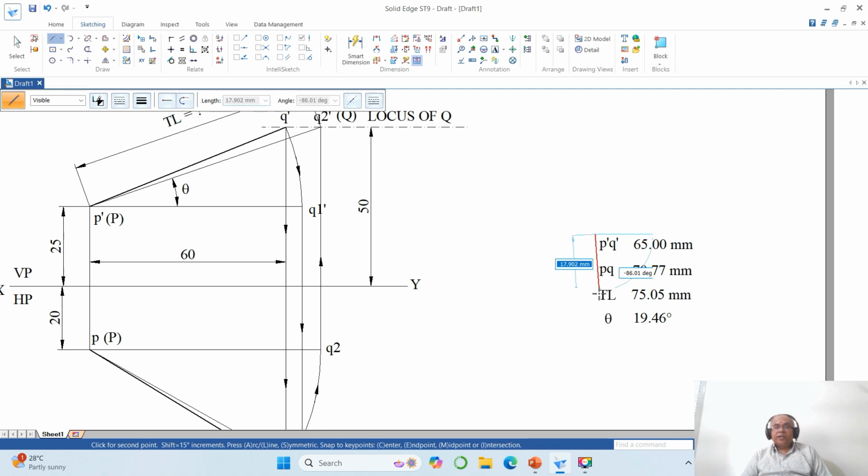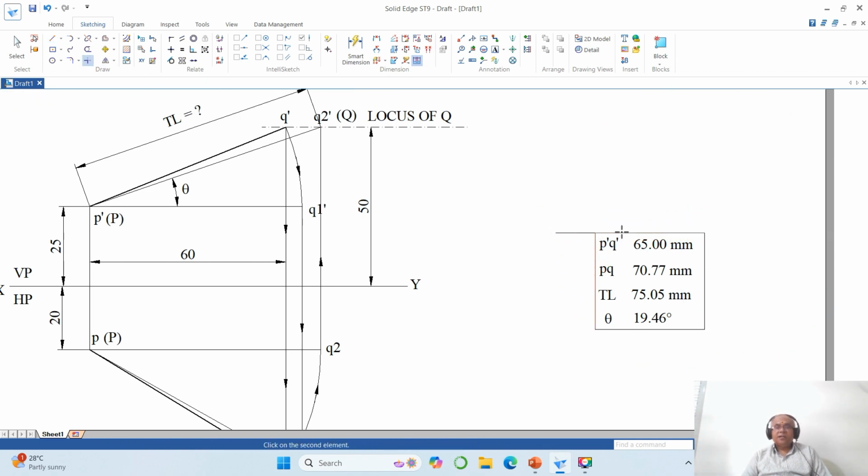Draw a vertical line of any length, then the horizontal line, then you take it here, then go to trim corner between this line and this line. Then go to move, enable copy, you select this line, right click on the first element.